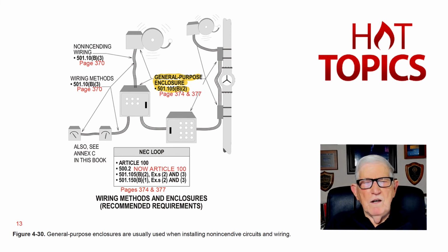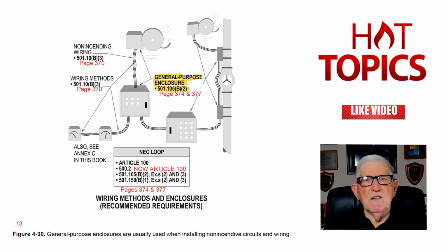And then you have your two major sections when you use non-incendive circuitry. 501.105b2, exceptions 2 and 3, or 501.150b1, exceptions 2 and 3.